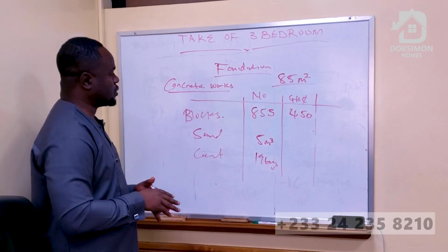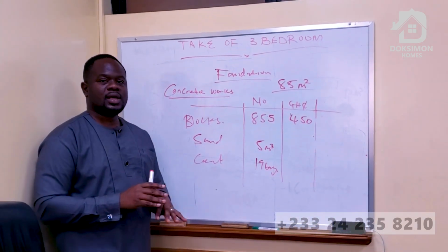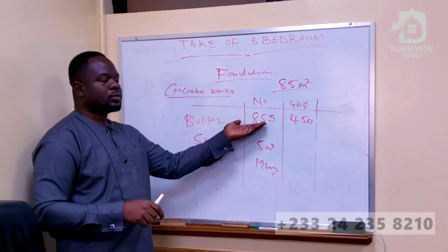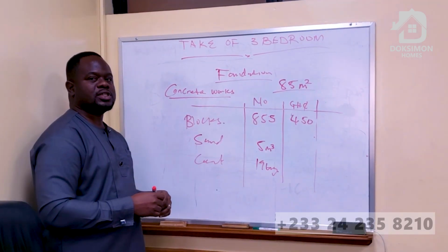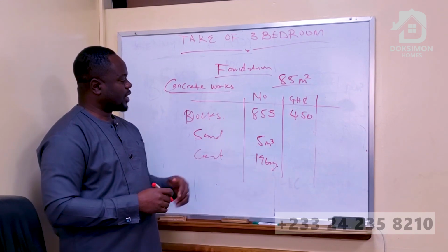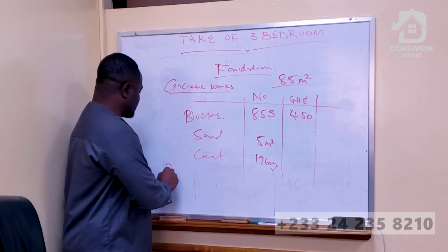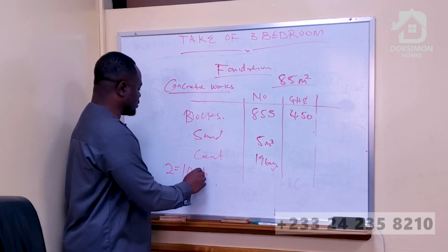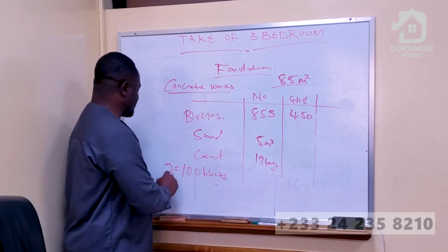There might be slopes. It might vary in areas as your land may be. You might need more or less of these blocks. And remember, every 2 bags of cement can lay 100 blocks. That is just by the way.